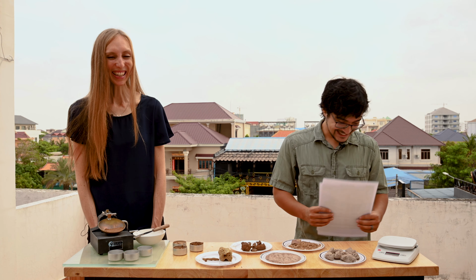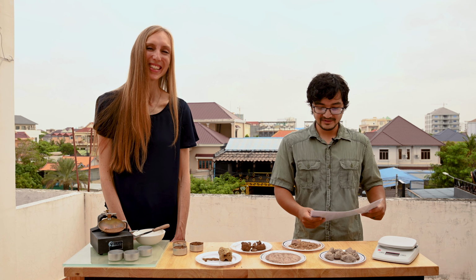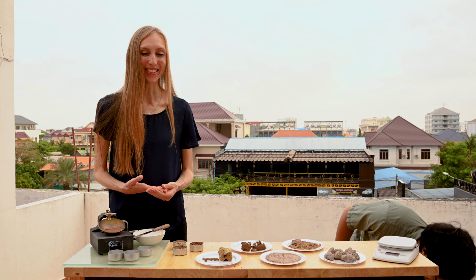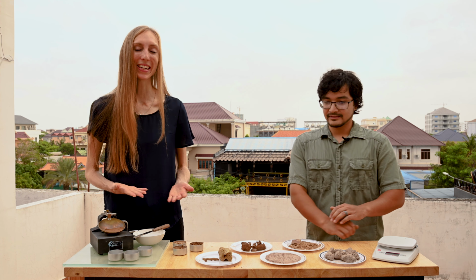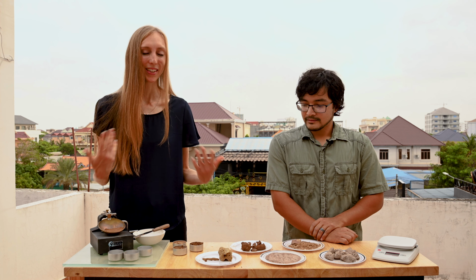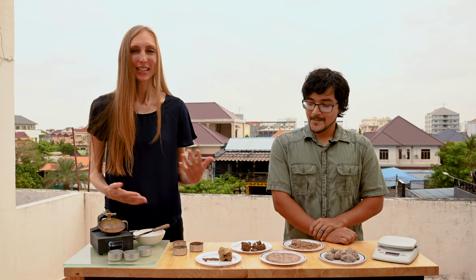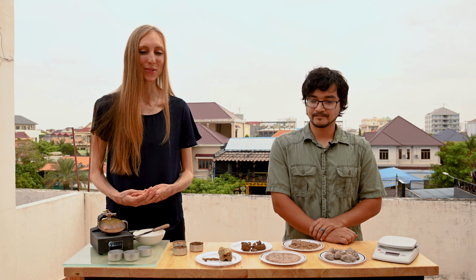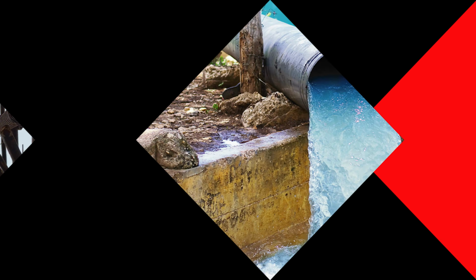So now we'll look at classifying some of the soils. In visually inspecting soils in the field, some important characteristics to note would include the color, the moisture, the texture and consistency, and the odor, if there's an odd smell, or cementation, which we'll discuss later.